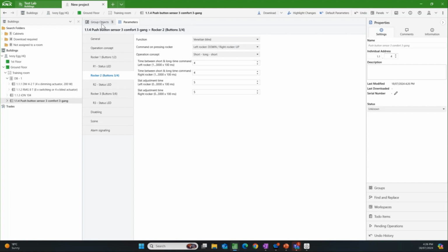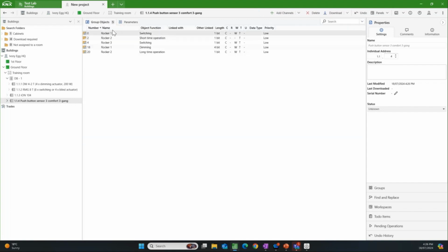So from that, if I look at my communication objects, and I put my functions in order of the name, the first rocker has a switching function when I short push on it, and when I long push on it, the dimming function. Gira's gone a step further here, and they've said it's up to you what you think should be a long push and a short push. We won't determine that for you. So you can use the long operation to drive the blinds, which is what we suggest, using the up and down operation, and the short operation to step stop. But if you had a customer that wanted it the other way around, a short push to drive the blinds and a long push to stop, you just swap these two around.